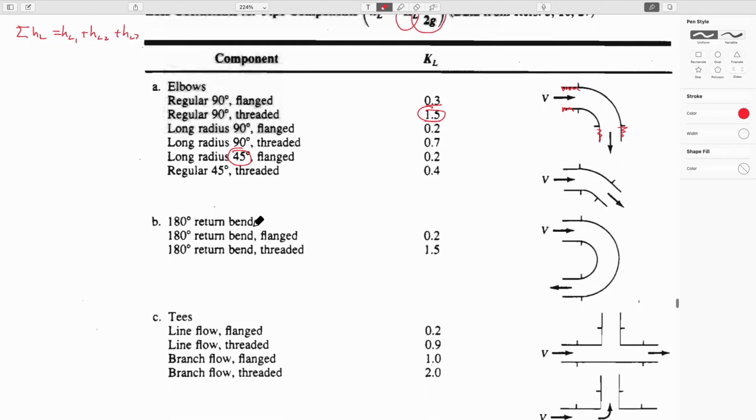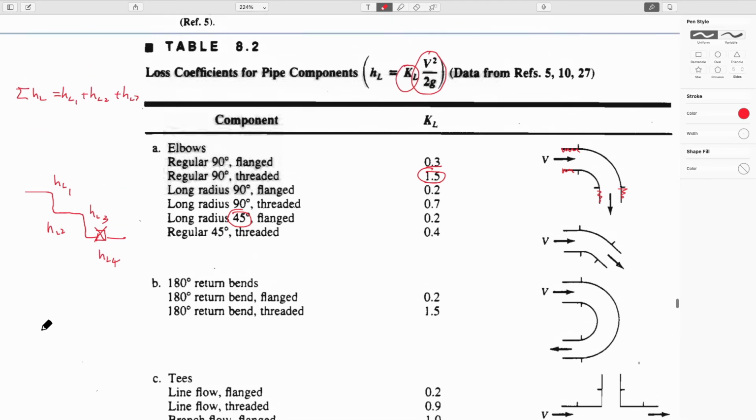So if you had a piping system that had a bend in it, a bend in it, a bend in it, a valve of some kind that's not closed all the time, then there'd be a head loss here, a head loss here, etc. Nothing more than that. So in the question, they're just choosing a single value. I guess the only point I was trying to make is that you have to be careful to choose the right velocity that applies to that particular head loss.